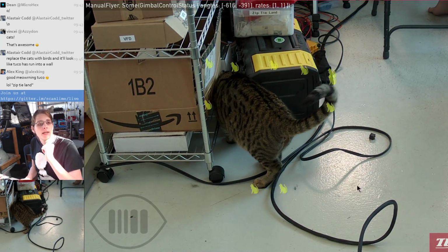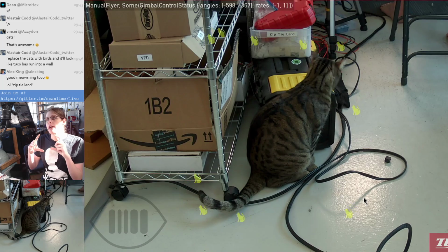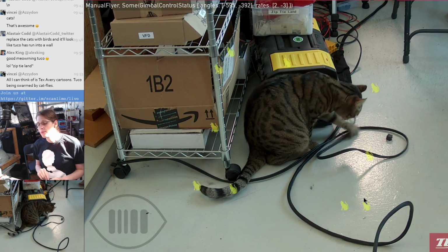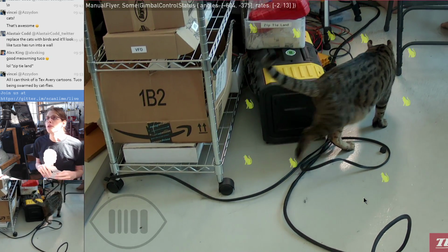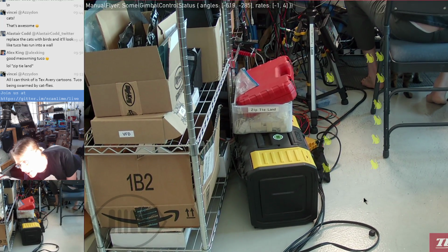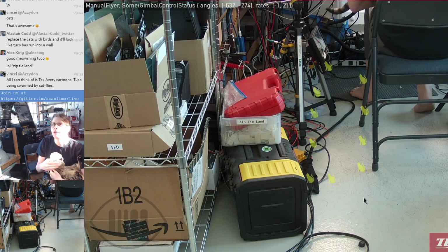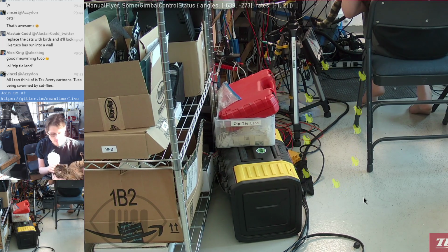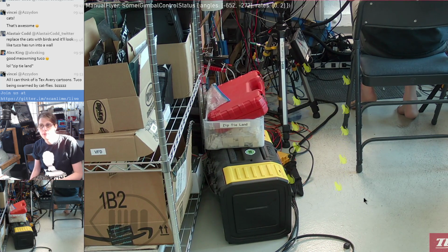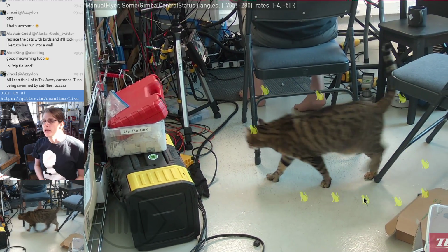So for that, I already described the original scheme, where it was looking at the center of the tracking rectangle versus the center of the camera and then multiplying that by a gain. And that was bad because it had no concept of this is close enough, don't move. So you ended up responding to every tiny movement with a bunch of jitter, which wasn't nice. It also had trouble responding to both fast movements and being stable in all conditions. So it was difficult to tune and didn't really work very well. Then I tried a different approach, which was just a hunch, which I think turned out to be a bad idea. And that's what it's doing right now.